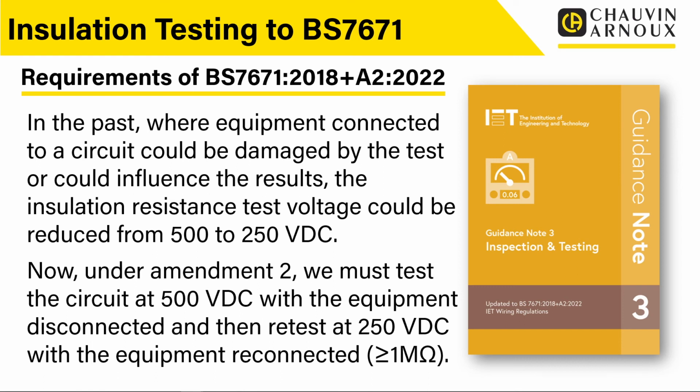So I think they're now trying to put the emphasis on saying, look, you need to make the effort to test at 500 volts. And the reason we're doing 500 volts is because it is above the supply voltage. We are putting this insulation under some stress. So again, I think in principle, we should carry out these 500 volt tests. However, I do foresee, particularly with electrical installation condition reports on existing installations, that it may be difficult to do this 100% as per the letter of the regulations.